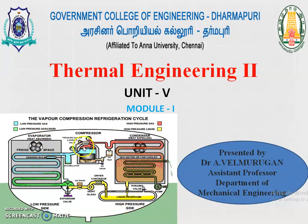Generally, in vapor compression there are two sides: the left hand side is the low pressure side, and the right hand side is the high pressure side. The liquid refrigerant enters the receiver tank. After that, with the help of the expansion valve, the liquid goes to the evaporator, creating the chilling effect in the refrigerator, freezer or surrounding room. We get the chilling effect from the evaporator section only.